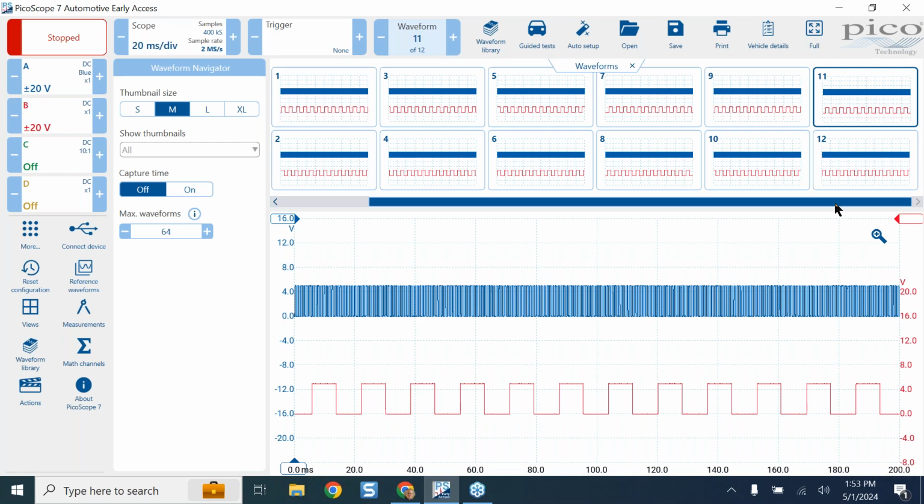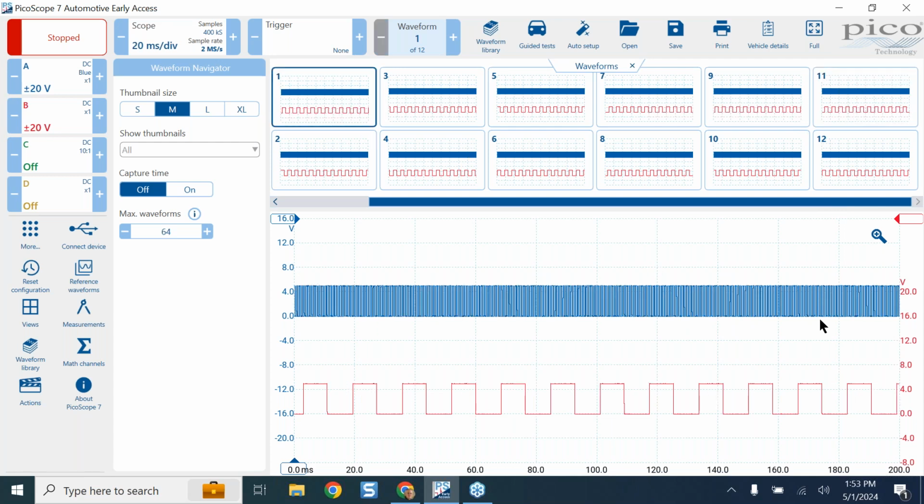That's what that screen is going to show, and so forth, all the way down to 1, which is a computer 11 down from me to my left. So that's kind of how the buffer works. As you start and stop the scope, it clears the buffer, and it continues to fill in those buffers for those waveforms, so you can stop the scope and scroll through and look.